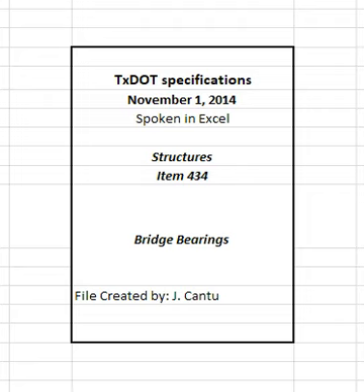3. Construction. 3.1 Plain and laminated elastomeric bearings. Electronically submit shop drawings for the complete assembly before fabrication of laminated elastomeric bearings with or without steel top plates or special components in accordance with the plans and item 441, steel structures. Provide a bearing layout with the shop drawings.